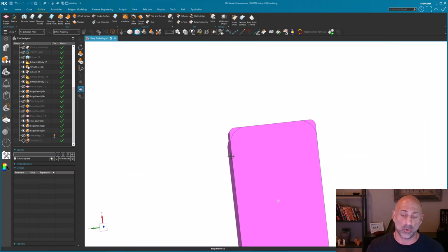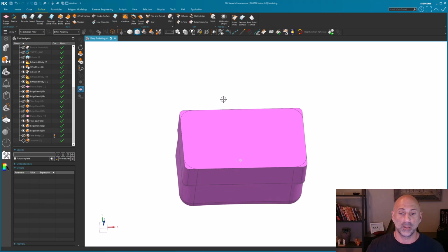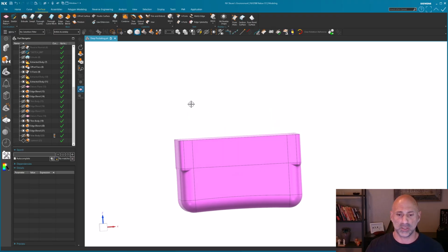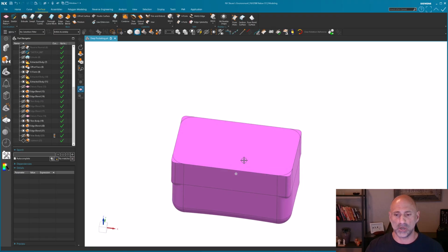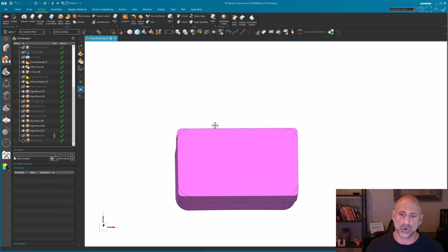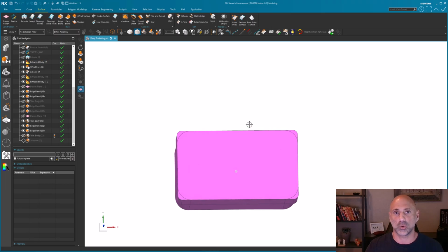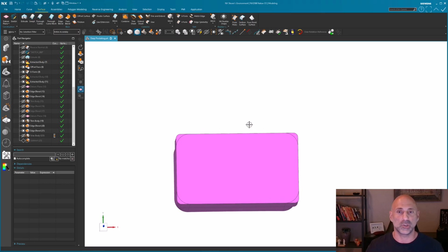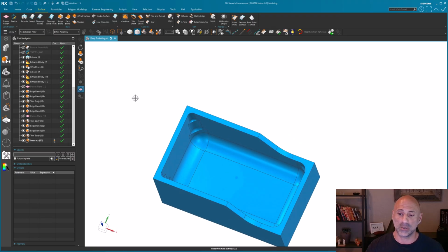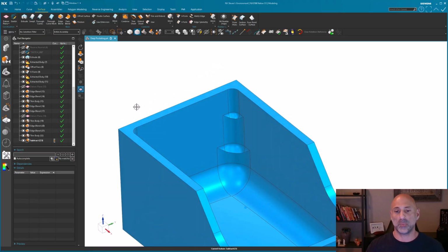Again, those driving corners are the ones where, if the tool's coming in, in this case the Z-direction is coming in, it's plunging in, and it's going to come around. As it comes around, it's going to go around these corners. So think of it as a loop, a racetrack of sorts. Like if you're driving your car around a racetrack, going around a hard corner versus a gentle corner makes a very big difference to the final time. And that's the same concept for your machine parts. So paying attention to at least those kinds of concepts is important. So if you end up with a part that looks kind of weird, like why? That's why. That's for the purposes of deep pocketing.